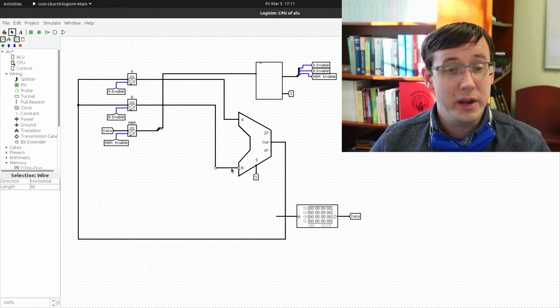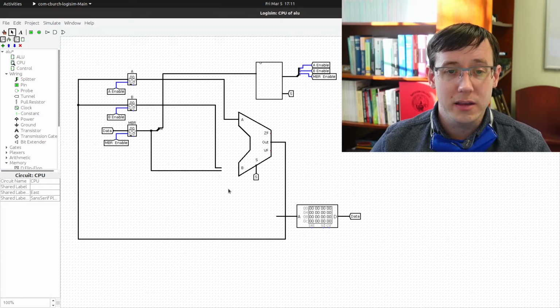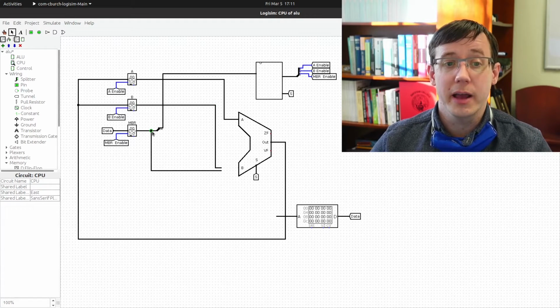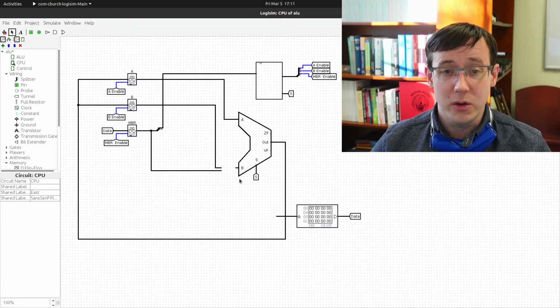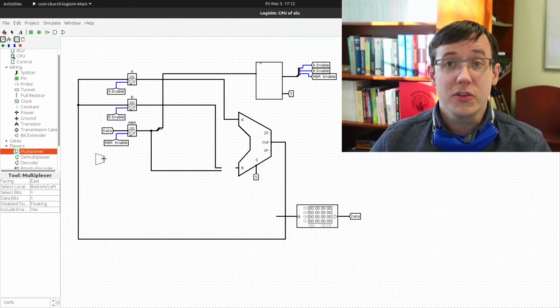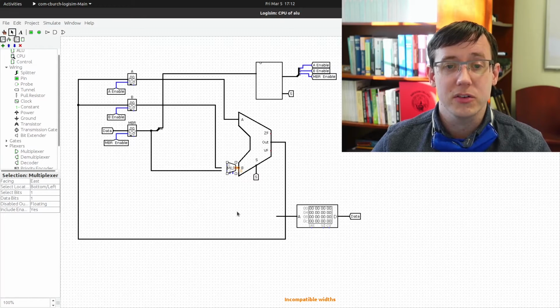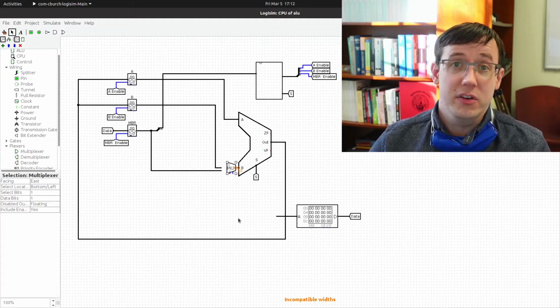So that means that we can just have a single multiplexer on the B input to our ALU, and this multiplexer will select between the B register and other possibilities as this input to the ALU, which we can, when we want, then just pass back along and enable one of the data registers. So the advantage here is that we don't need to have a separate multiplexer on each of our registers, and we can get away with just a single multiplexer on our input to the ALU.